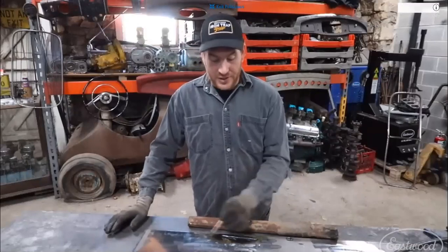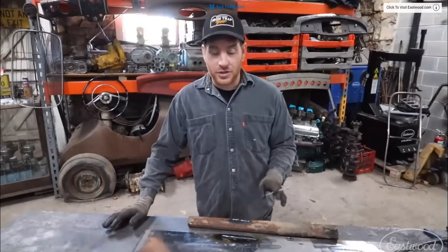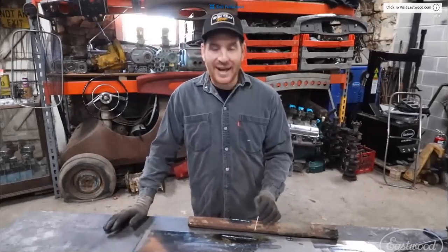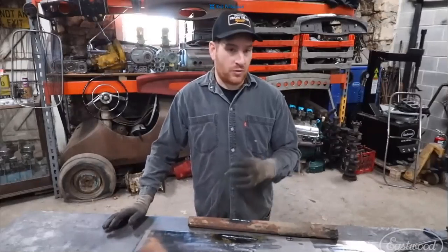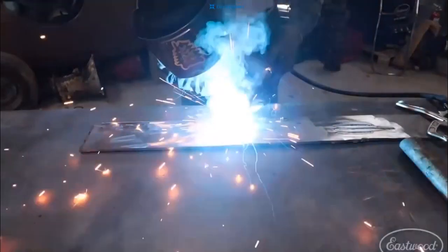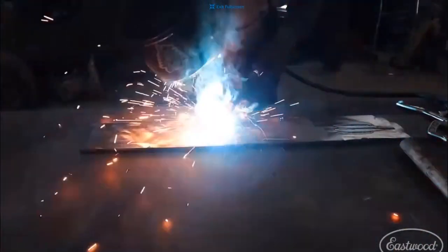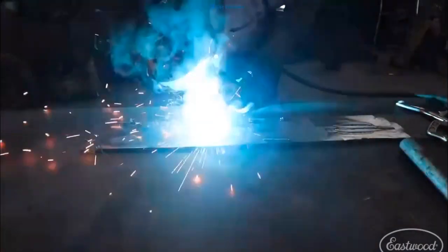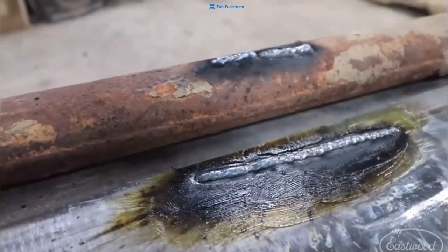So this is a clean piece of metal that I hit with the grinder, cleaned it all. Should be good, but it has some grease or residue on it that we maybe didn't notice or got on while we were working on it. While we were welding, you will notice that it created that black soot right around it, actually made the grease kind of bubble up and get more liquid-like. And now you can really see the grease on there, whereas before it was just a real fine film.